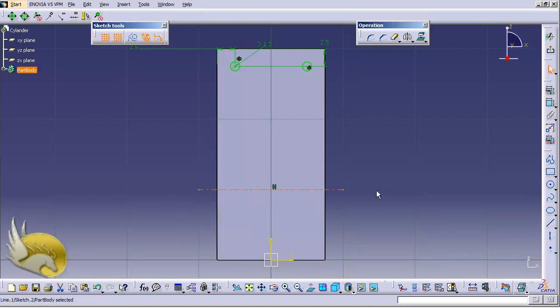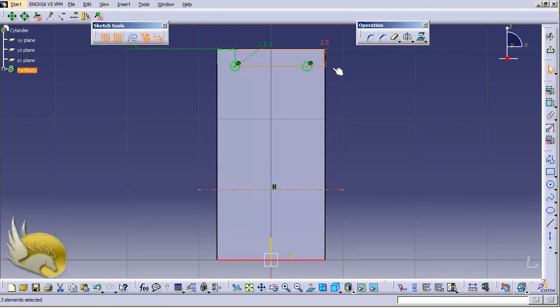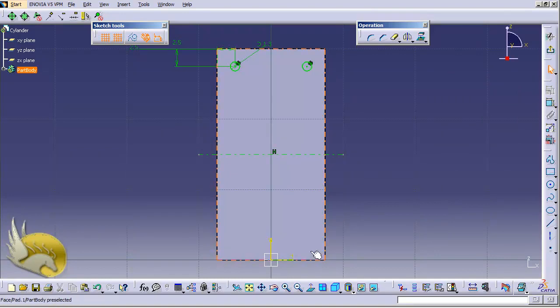And this axis, I select this line, and this, and add a symmetry. Or I didn't select the correct shape. So I move this here, and again select this line, and this axis, and add the symmetry now here. You can see that the axis moves up because I had a constraint that doesn't let the top part move up.